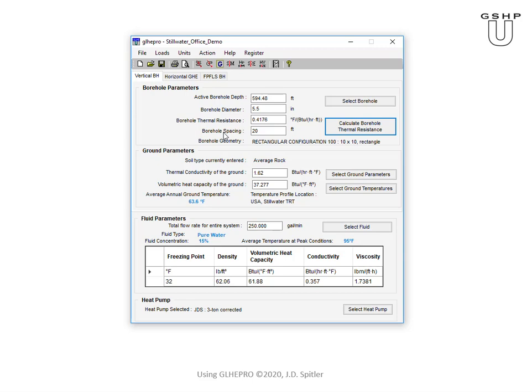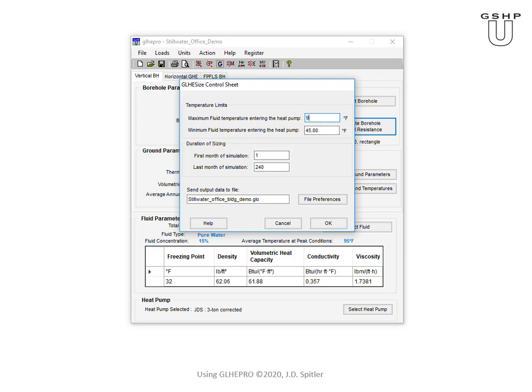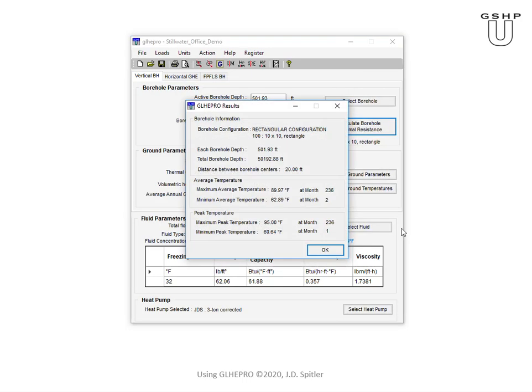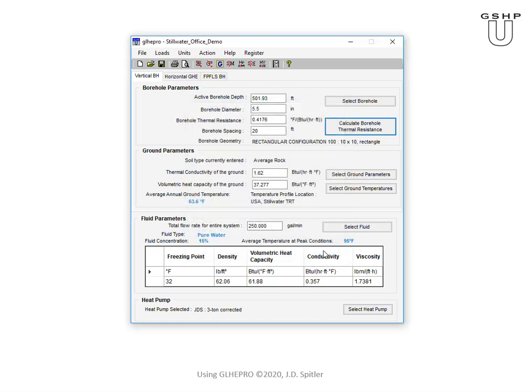So if we just went up to 95, then we drop down to 502 feet. So it makes actually quite a bit of difference. The problem is we'll have less cooling capacity at that point, which depends on your selection of your equipment. Also, our efficiency may, well, the cooling efficiency will be better if the temperatures are lower.